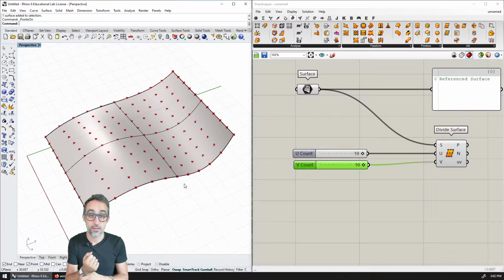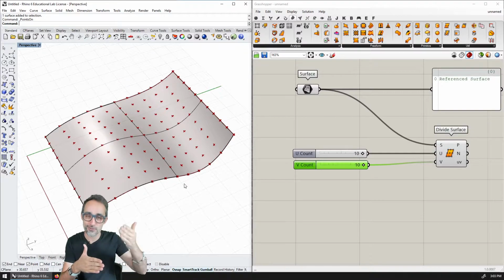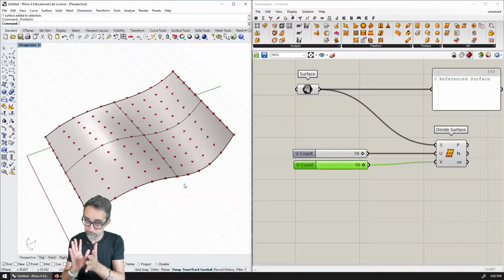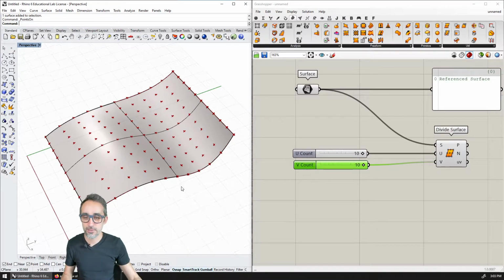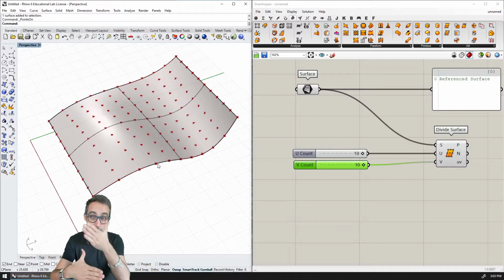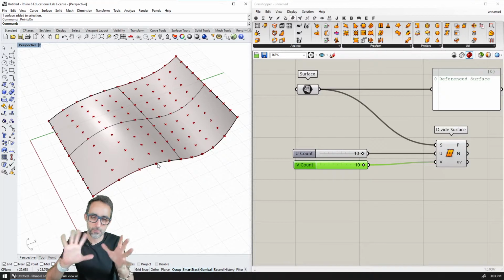So this is just to say that UV subdivision will not give you points that are equally distant in Euclidean space. They are equally distant in internal UV distance, but that may not have a constant rhythm in Euclidean world coordinates. Okay? So that's why I was saying before that this is a little bit of a shortcut, because in the original monument, the blocks are actually distributed orthogonally in a grid, which is not going to be the case here. But anyway, just an approximation.